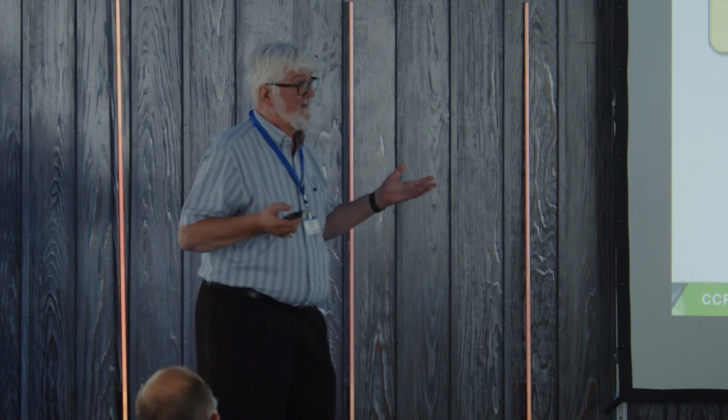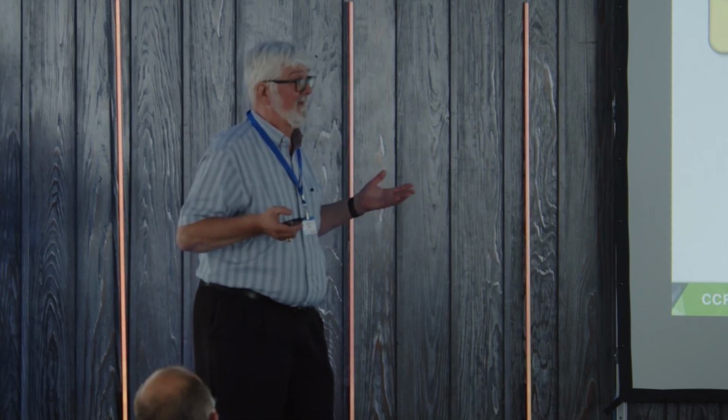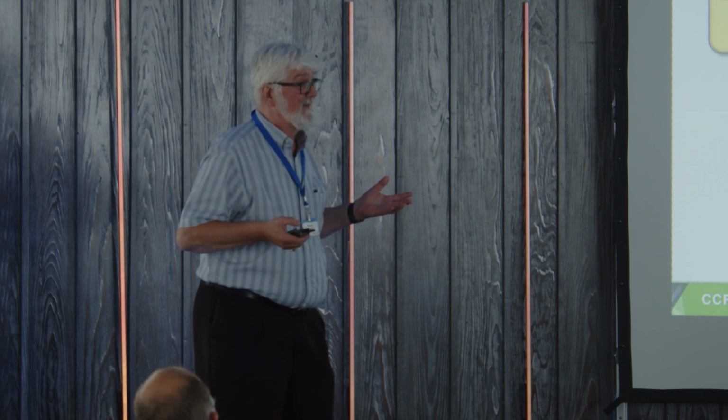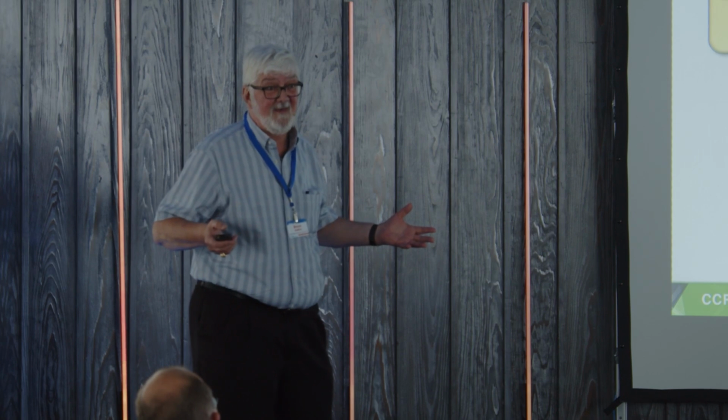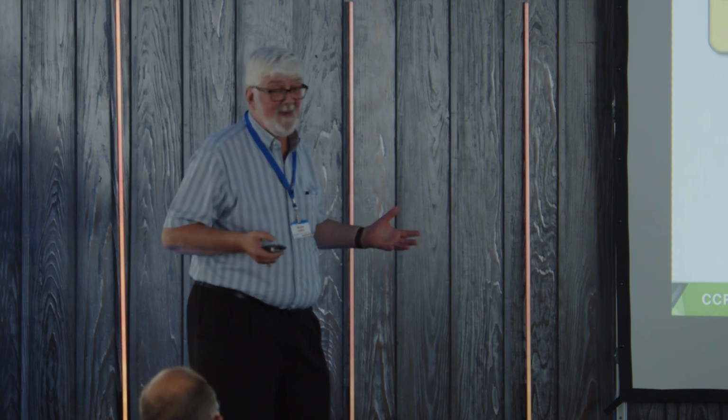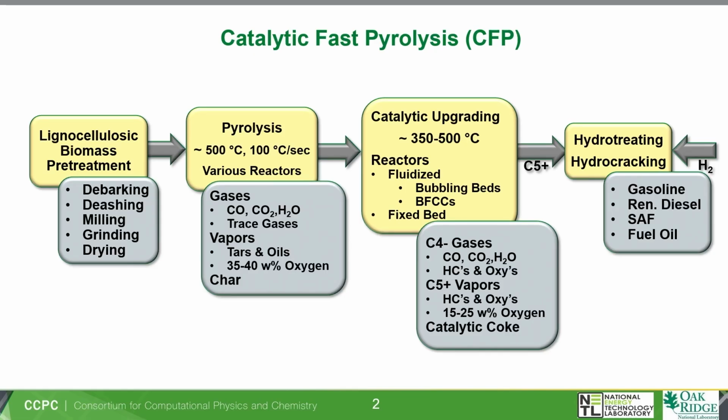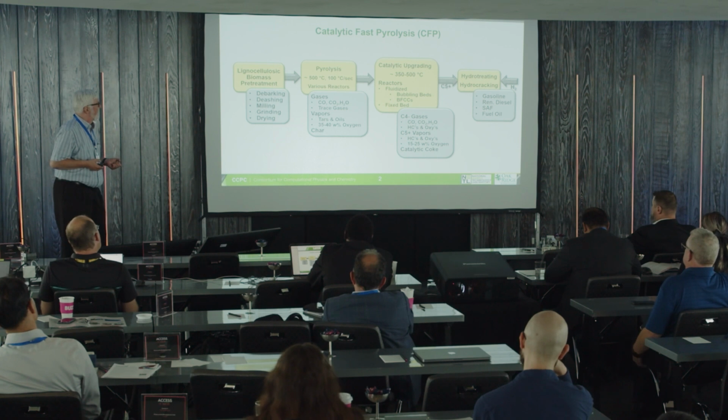Since I've already said I worked for Kior, we tested over 2,000 catalysts in Kior, and there's still a lot of work to be done to optimize the catalyst when you think about how much optimization has happened in FCC over the years, how much catalyst knowledge there is. Okay, you can use fluidized beds. My preference, of course, is the BFCC, but you could have a process that uses a bubbling bed or a moving bed, larger particles. You can do it in fixed bed. Our buddies at NREL, I'll be talking about in just a minute, have done quite a bit of work using a fixed bed upgrader. And there are advantages, of course, and disadvantages, as you would expect.